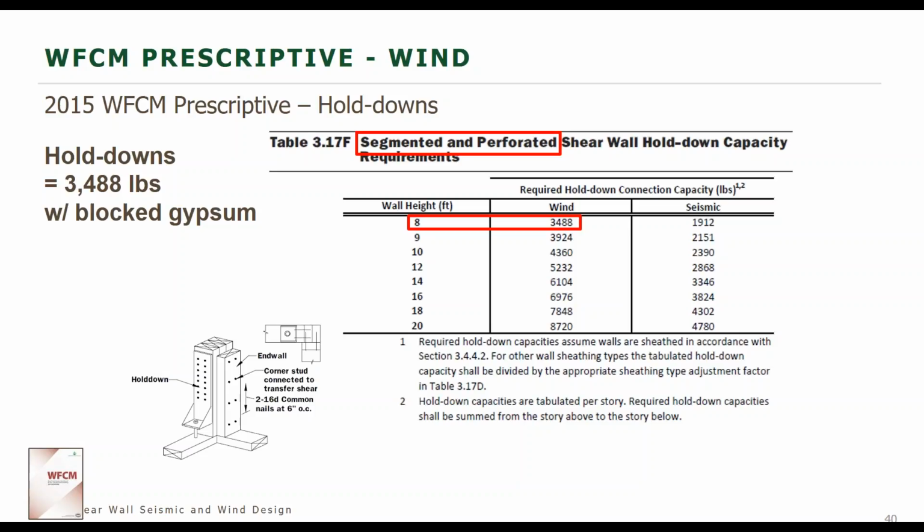Correct. That's specified in C112 in the commentary. Yeah, so we do assume both roof and wall, and maybe even a portion of the floor dead loads, to offset those straight wind uplift loads.